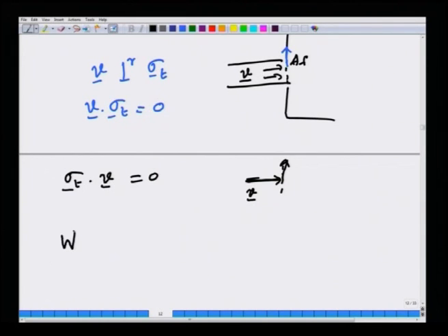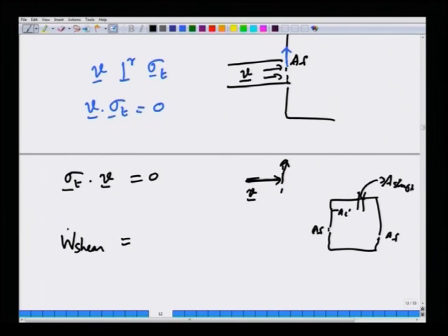So, for the shear component of the work, there are three types of areas that we said. Let me just draw them: the internal area, the flow area through which fluid is entering and exiting, and the shaft area which is cutting across the control surface. So, there are three contributions to the shear work. One is due to the shaft work, which we have already separated out, so we do not have to include it.